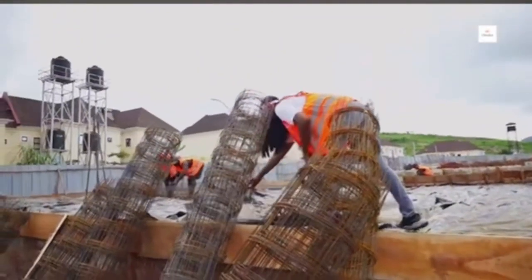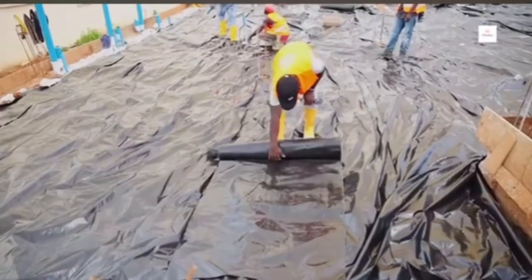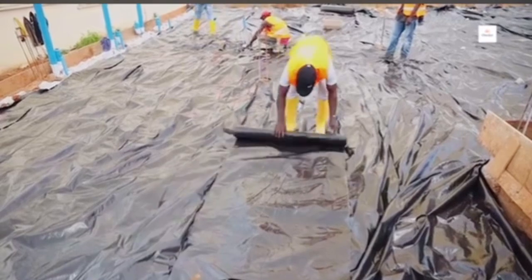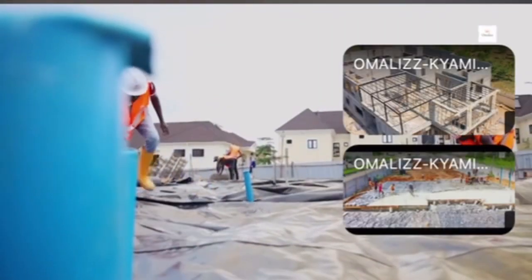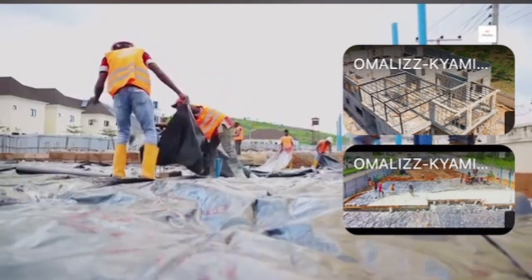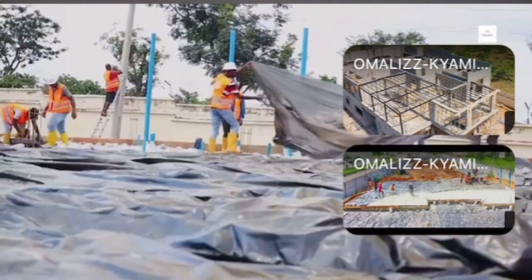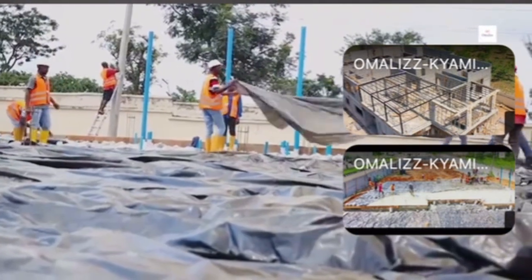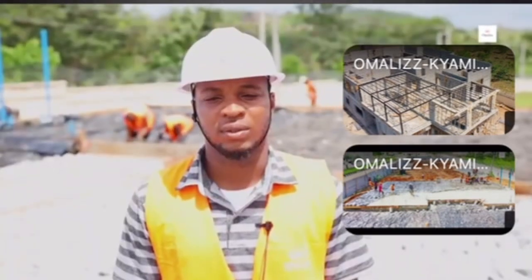So the workers are now laying the DPM and the BRC. The essence of the hardcore is to break the capillary action. The work of the membrane is to resist that capillary action from penetrating the oversite concrete, while the BRC is for absorbing the shocks or reverberation on the oversite concrete. That's what we are doing right now.